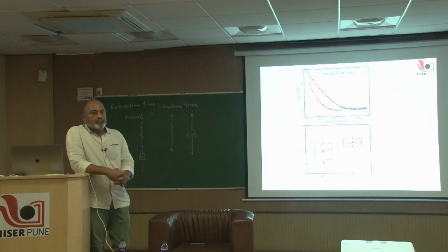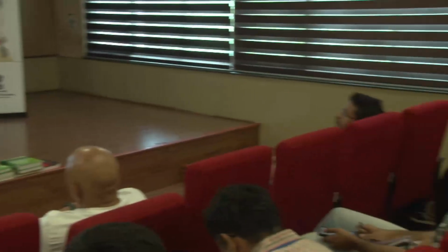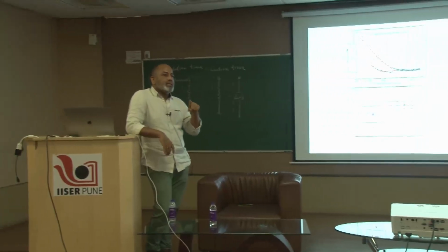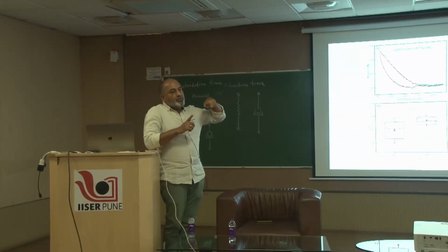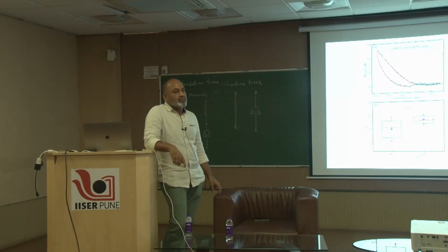When we are applying force with a frequency, in an oscillatory measurement, is that frequency probing a certain process with a certain time scale? Exactly. In order to do this full characterization in an oscillatory way, you do one measurement and measure the loss tangent, then another frequency, and so on. If the system has one relaxation time scale, G prime and G double prime, storage and loss, will cross each other, and the inverse of that frequency is your single relaxation time.